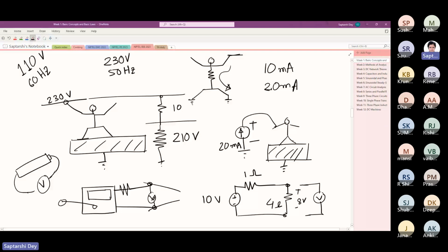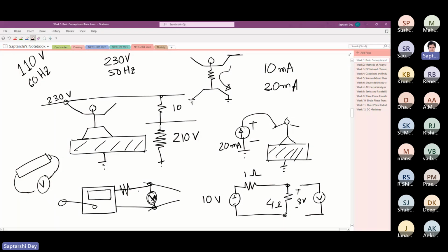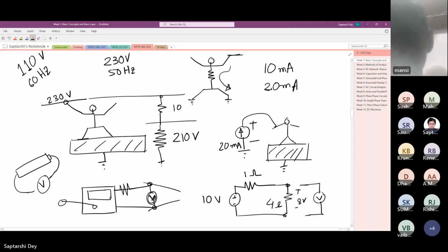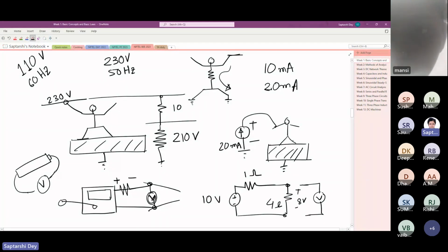Similarly, for the Megger also, if you do not touch, only put the voltmeter and rotate the handle, you will get 500 volt, maybe. But as soon as you touch the terminal, the current starts flowing and there is a drop across this resistance. What you get is the source voltage minus this drop, so a very small voltage at the terminal.